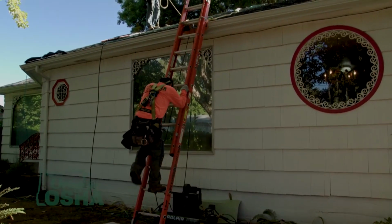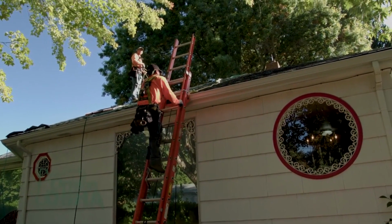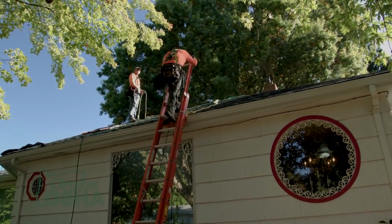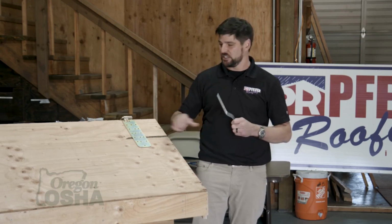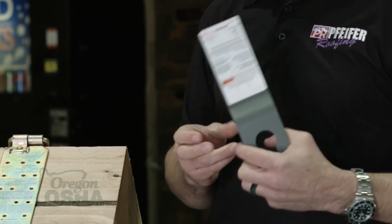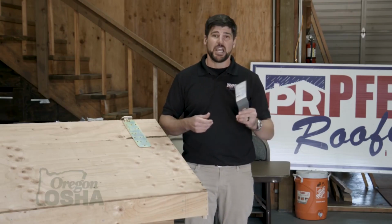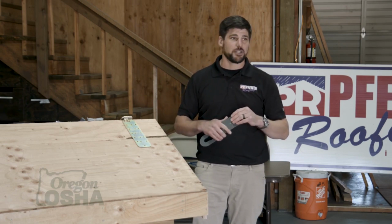And so what this does for us, when we come back to clean the roof, if we need to inspect something, this anchor's already set up for my guys to be able to set their ladder, walk straight up with their harness on, and clip in and not have to remove any roofing to set an anchor. And so this is just a standard practice within our company that we leave these on every single job. And again, when you install permanent anchors, ensure that you read the manufacturer's specifications when installing these.